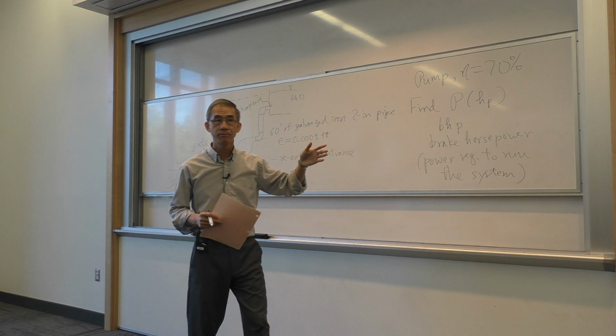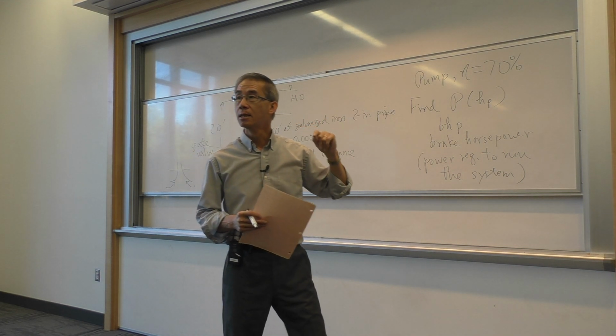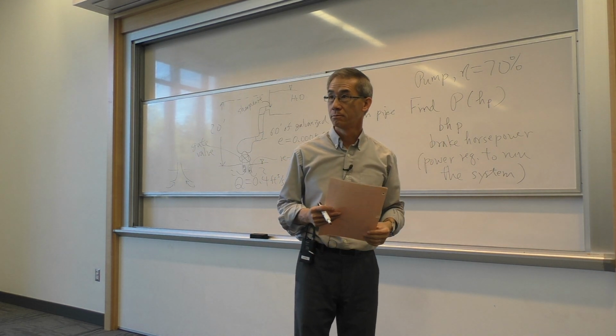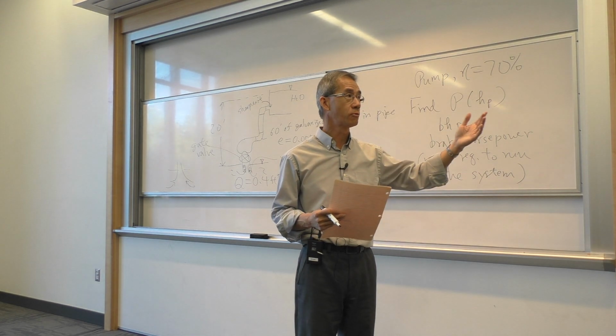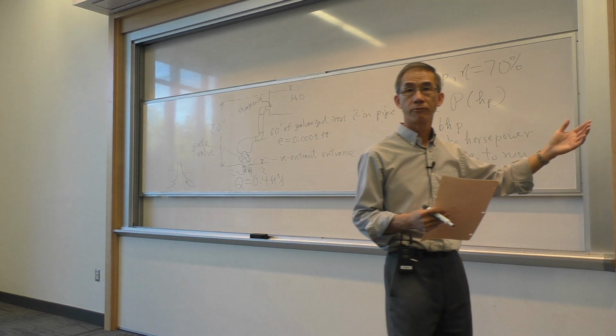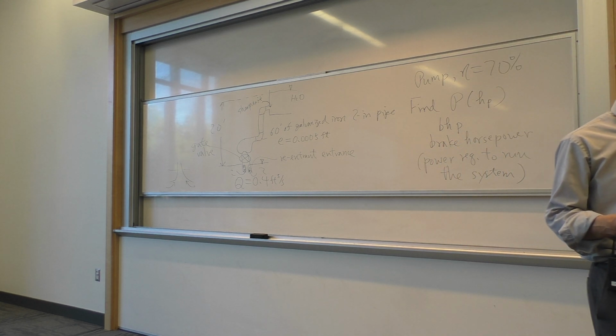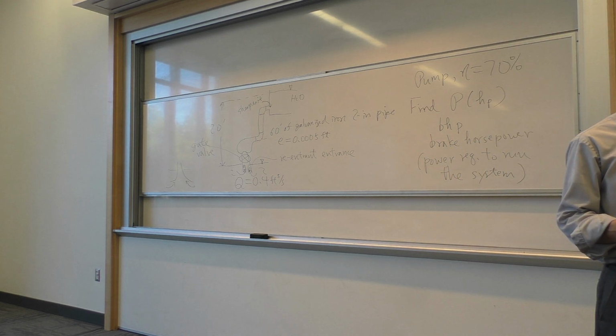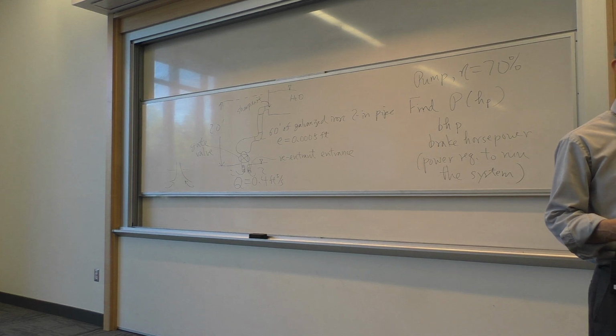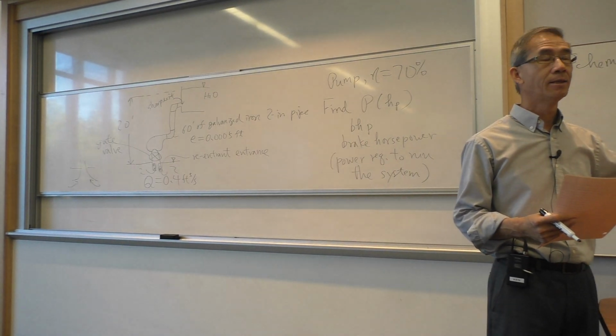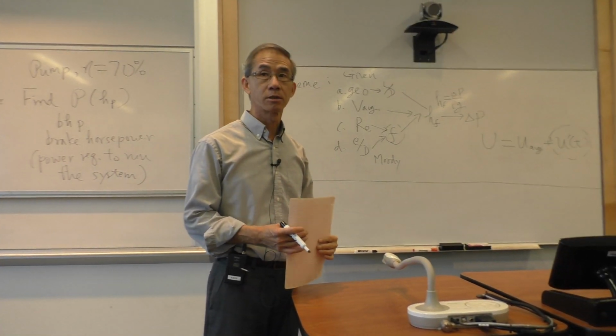The table you can look up depending on the geometry of the device, and it's all empirical. But they are work done before, so you can look up for a given device with a valve that is a gate valve that is 50% open with this diameter and so forth, what is the estimated losses due to.